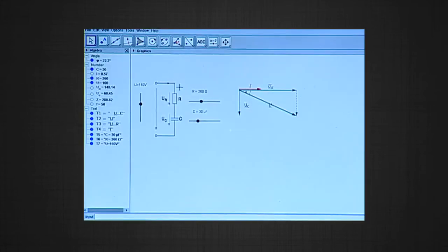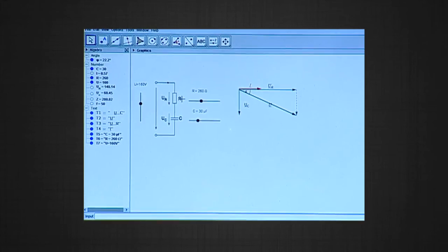Here we will see how alternating current varies across R and C when the resistance and capacitance are in series. We have given two buttons here in this file. If we change the value of R, you can see in this phasor diagram how it is changing, or this vector representation is showing how the values of I and V are changing. Suppose I change here C, the value of capacitance. So, how the vector or the value of voltage and current varies. This way we can show how the voltage varies and current changes across R and C when both are in series.